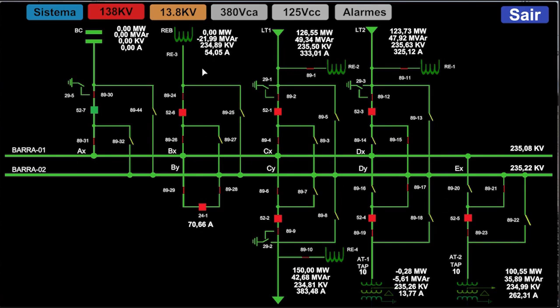Let me give another example here. Bus reactor. If I open the bus reactor circuit breaker, the voltage will rise. So the voltage goes up. If I close the capacitor bank, the voltage will rise even more. It went up to 200. All of this is calculated, folks.